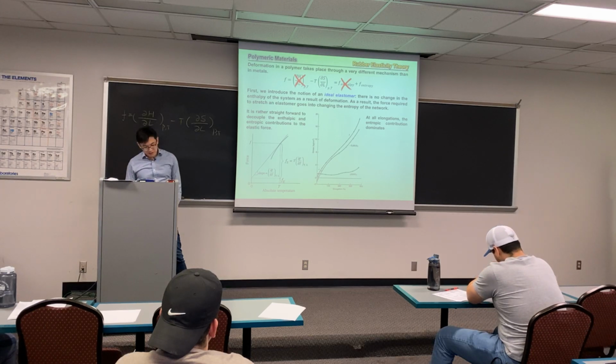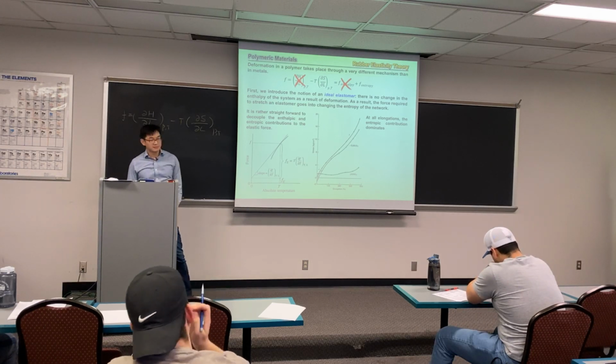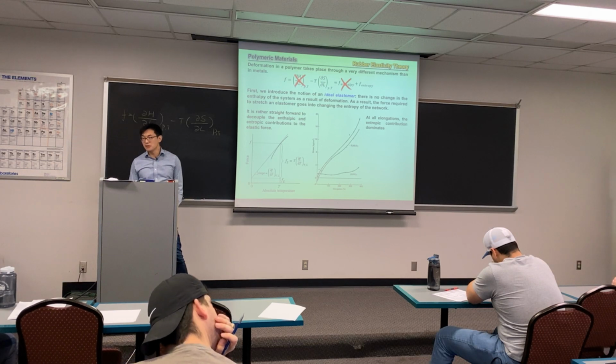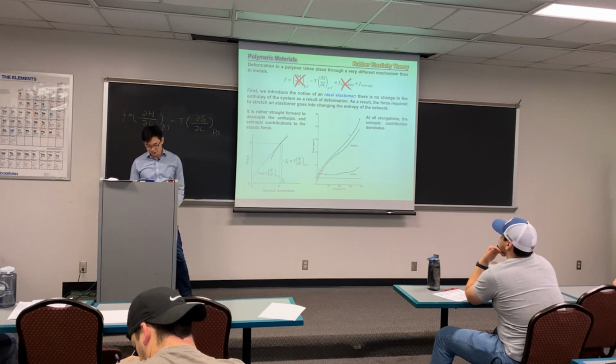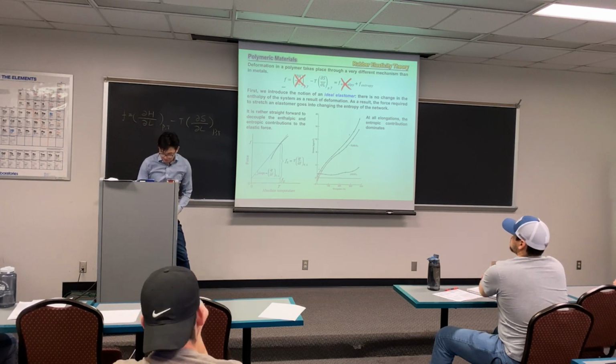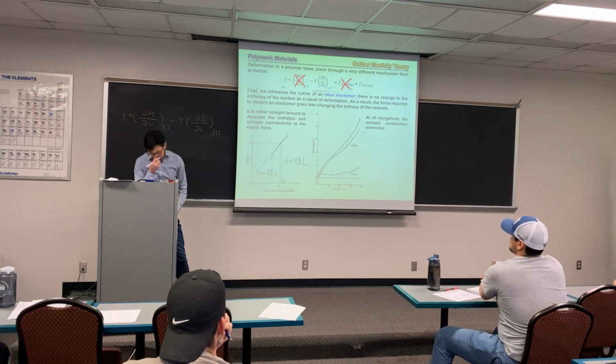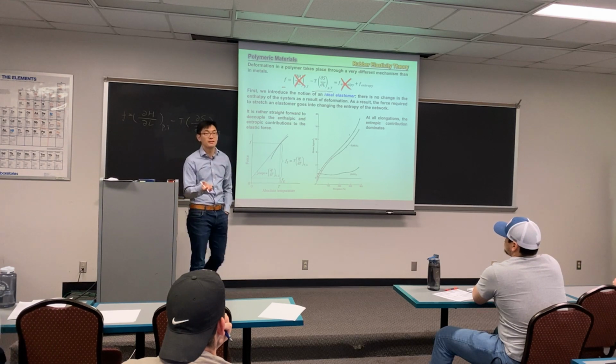This simplifies the problem a lot. Why? If we assume there is no energy contribution, then your force is strictly related to the entropy change during the deformation of a polymer chain.